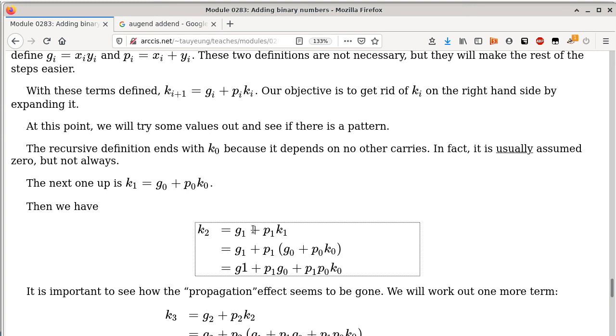That is a nifty trick, extremely nifty. In the second lab, the one that has to do with the carry lookahead adder, you have to use the final form of each carry bit for consideration. Do not use just the first one. You have to use the final form of each carry.